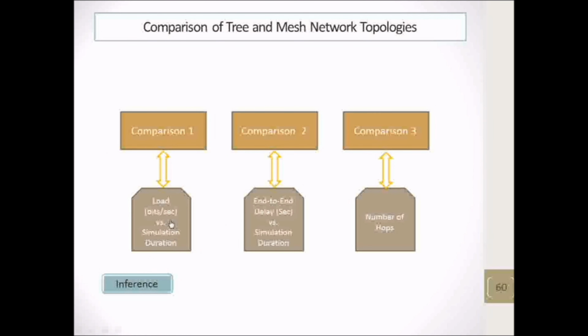Now to set up the hardware for serial communication, we have to see the requirements. In the forest area, we require the Zigbee module and its associated power circuitry. The Zigbee module is connected to the microcontroller, and the microcontroller is connected with the sensors. Similarly, in the monitoring area, we require Zigbee and its associated power circuitry, and the PC where the server is implemented. But Zigbee and PC cannot be directly connected, so we are using a MAX232 logic level converter. If this setup is done correctly, the wireless communication takes place successfully.